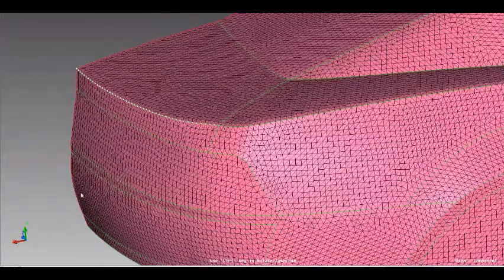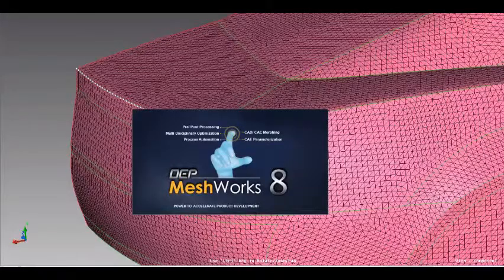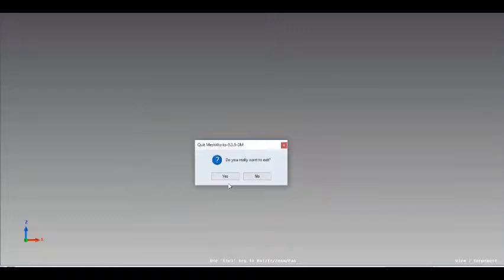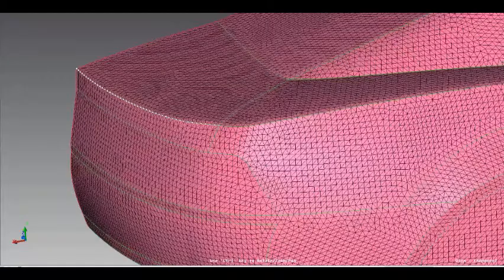Okay. So it doesn't care if you select the fillet surface or the planar surface or something like that. You're basically just selecting whatever surface you want, and you're telling the software what kind of change you want. For that particular situation, we only selected just those fillets in that area that we wanted to optimize. Then we go to the fillet radius change function, and that's where it's automatically going to do the morphing on a percentage basis.